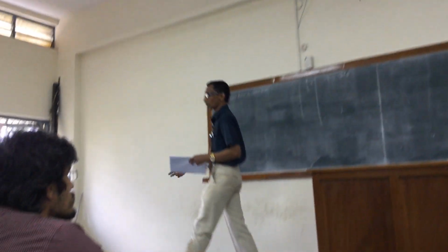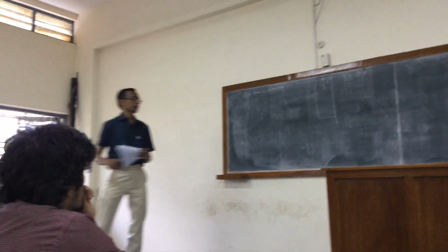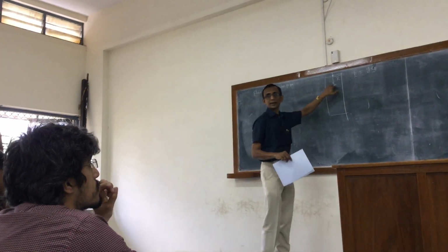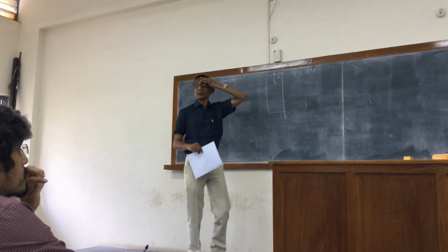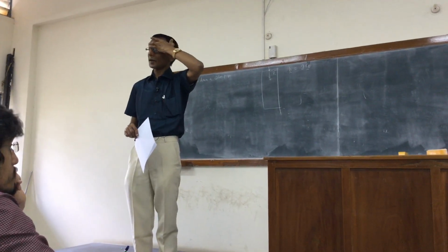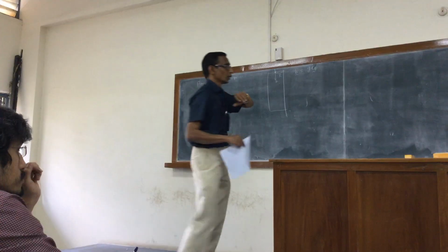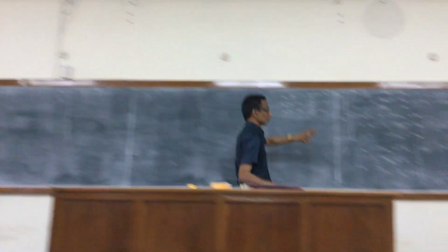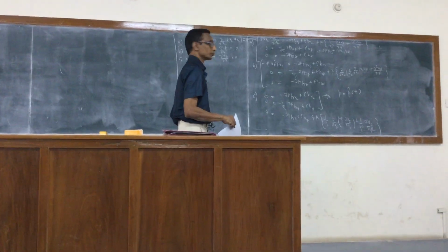So the inertia terms all vanish, and the way I have chosen the flow direction and the Z axis means that the components of the body force in the RC and phi directions are zero. What these equations then imply is that the pressure derivatives with respect to RC and phi are zero, and so P is a function of Z alone. Right?